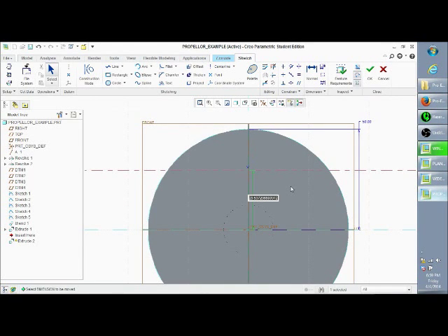We want to put this one, sorry, you don't want it to be from that plane. Sorry, stay with me. So we want to select this inner circle and this outer circle, and select off here to the side. We can actually just delete that reference dimension. Simply hitting the delete key will do that.